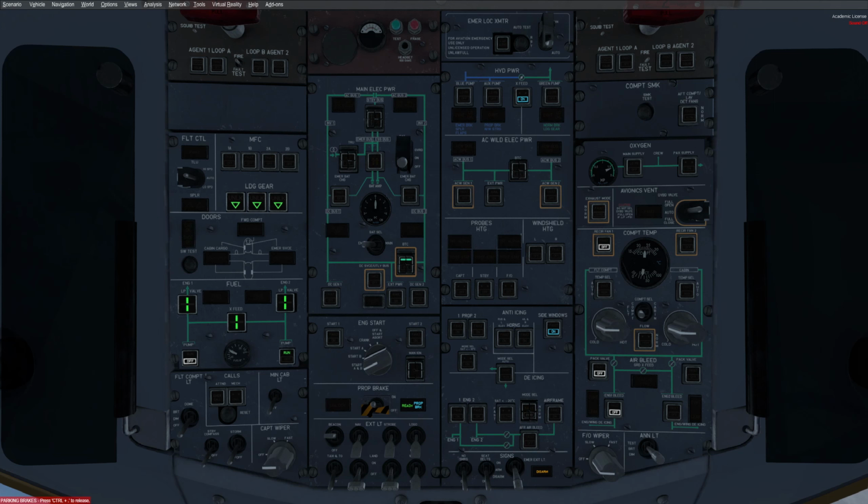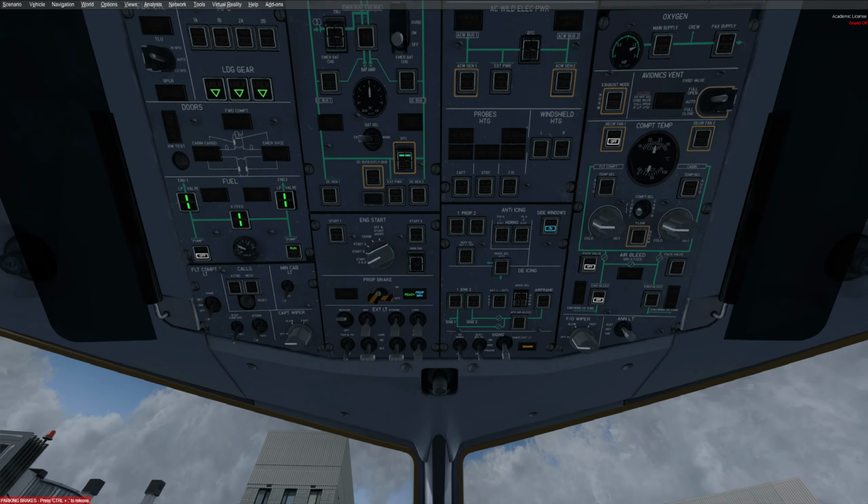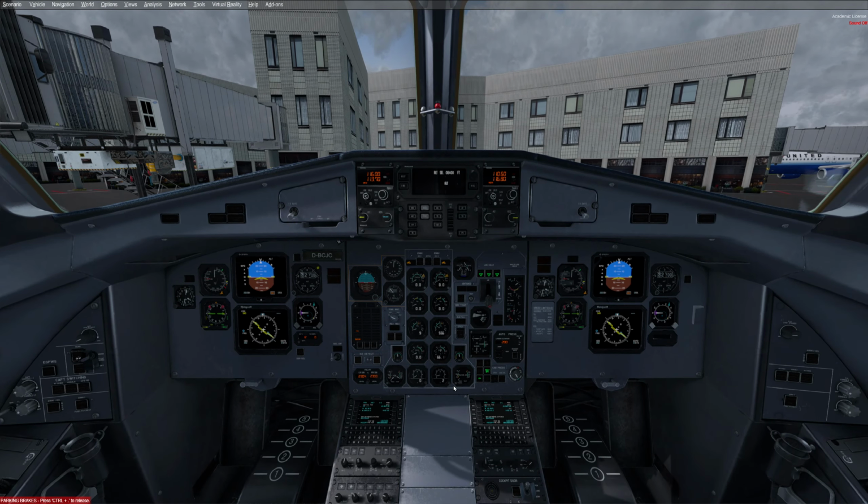We can set our altimeter. We can set our landing elevations on that business right here. Like if it's at 300 feet, we can set that to 300. The power management here is on takeoff. We can then check our charts for weights and takeoff speeds, and I found some really good material on that that's very handy. We can set our speed bugs over here.